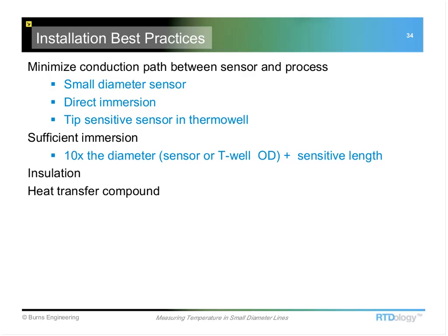But for those situations where it is allowable, it does really help speed up the response time, but it also can help minimize some of the stem conduction by concentrating that heat transfer between the tip of the sensor, where the sensing element is, and the Thermowell that the sensor is installed in.